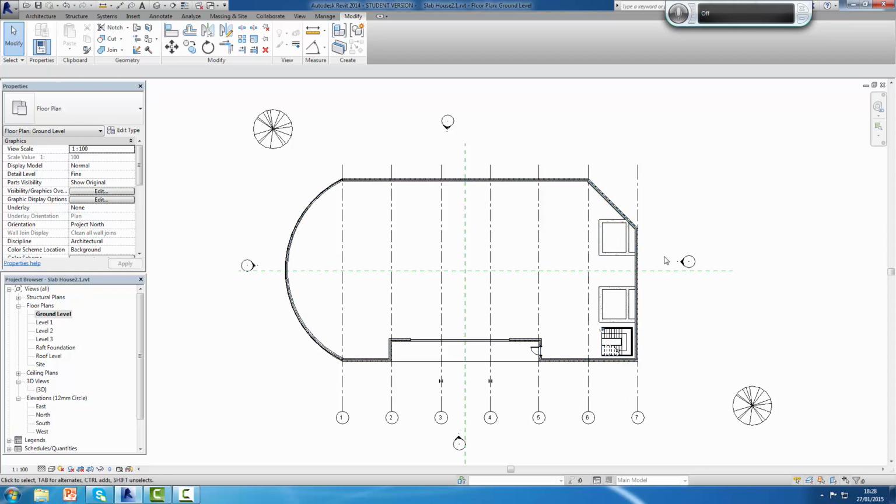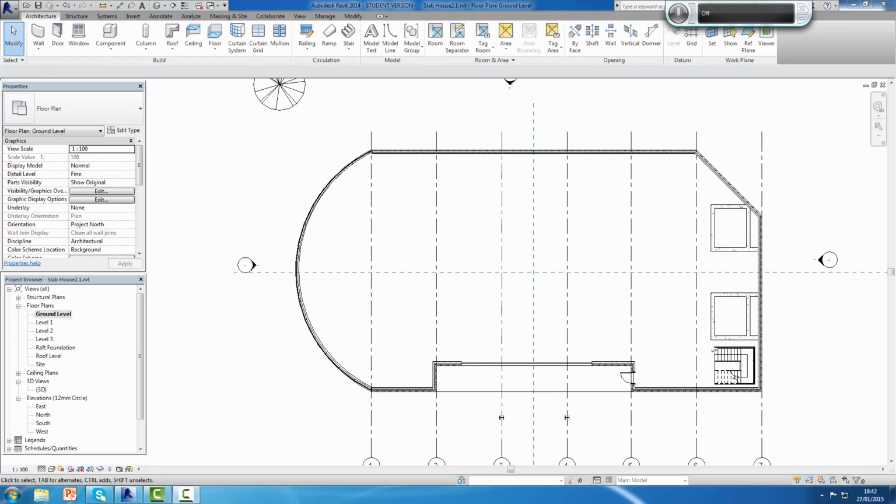So again, we'll go a bit further on and we'll put some more walls in, and we'll put some more shaft in. We'll lift that shaft up. Right, what I'm going to do next is add some walls to the actual ground floor itself. Now I'm just going to concentrate on the ground floor. As I say, you can start at whichever level you want. You can add what you want, and a little bit later on we'll use the copy command, where we shift them to the floors.